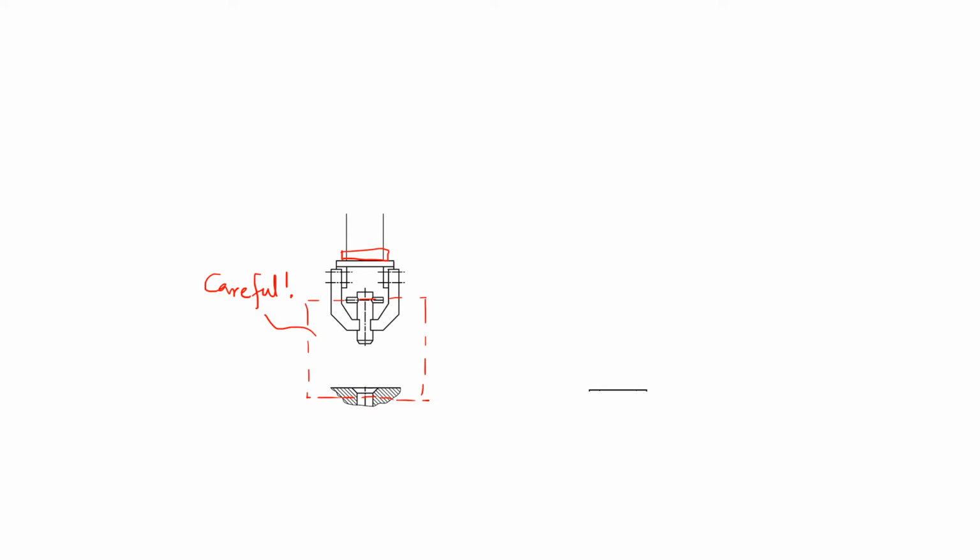And also this path now needs to be handled in a fashion that you follow a straight line as well. So this path needs to be extra carefully planned. And oftentimes when the robot needs to perform the insertion operation, some additional requirements may be added. For example, the wrist compliance. And that may also place some additional requirements on the path planning exercise. In a nutshell, you can readily identify that this whole activity needs to be planned in a methodical fashion.